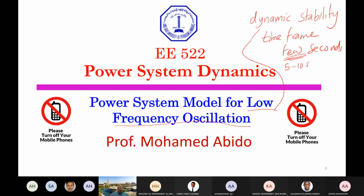So for dynamic stability, if we mention low frequency oscillation, we will have the synchronous generator model. In addition to this, we have the exciter model. So our model now includes the synchronous generator and exciter model.